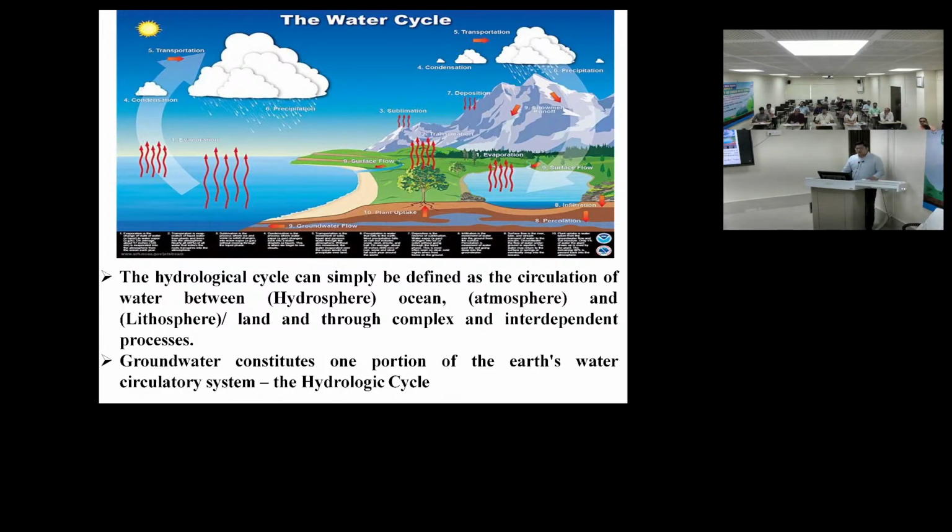The lateral movement of groundwater is very slow, around 0.01 centimeter per year. That's why, when you extract water, it takes time to recharge, because the source is somewhere else. Ultimately the recharge of the flow of groundwater, the base flow, depends on the gradient also. So the groundwater that we extract can have its recharge area 10, 20, 30 kilometers away. That's why finding the recharge area and all those things are important.